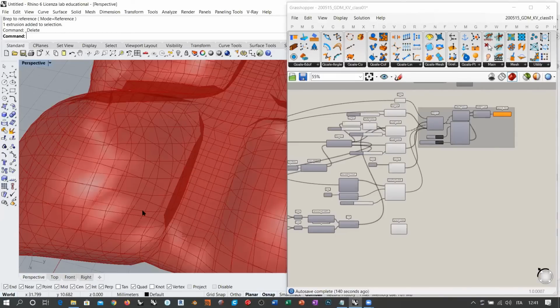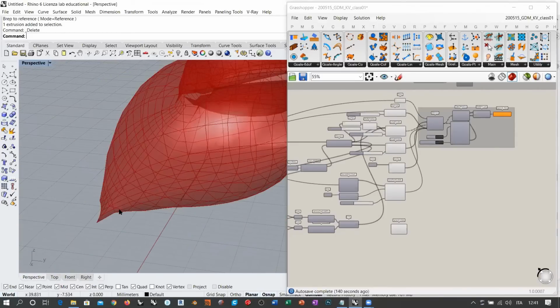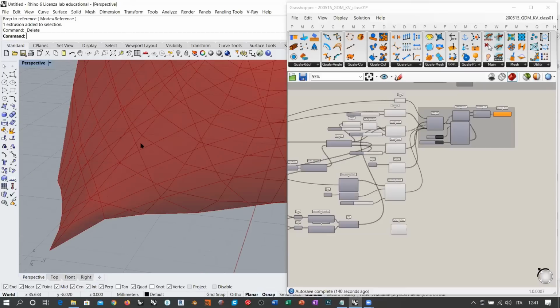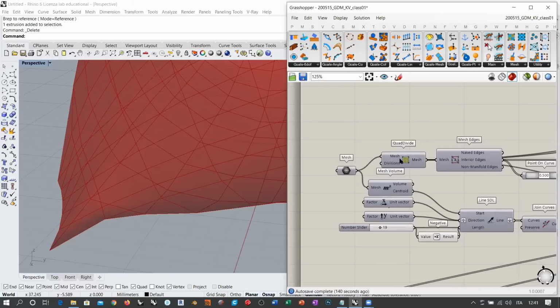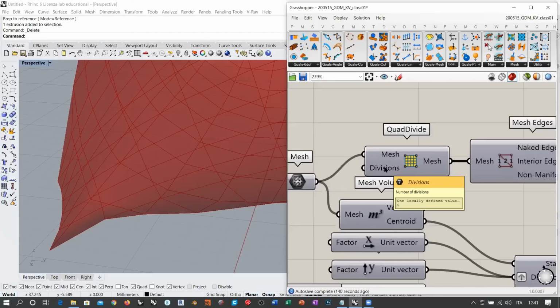But if we work with the original mesh that we have, the sides are actually being represented with more edges, because our initial quad divide was also dividing the polygon representing the height of the box, which was just 1, into 5 polygons. So we have very small edges along the height of the original box.